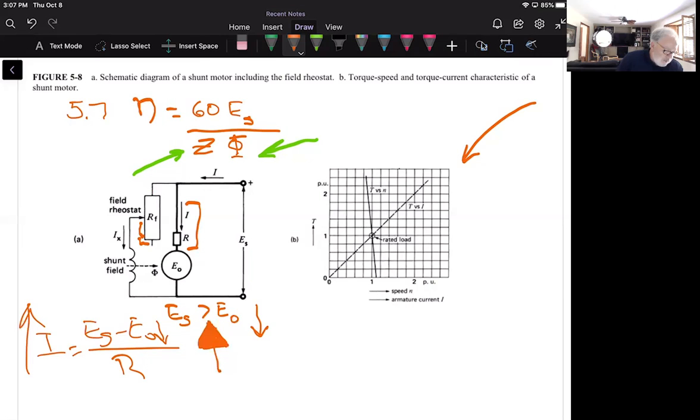But for shunt wound motors, shunt wound parallel, this method of speed control enables high speed to base speed ratios, and you can actually have this ratio up to 3-to-1, and strictly it's done by varying the flux using a field rheostat in the circuit.